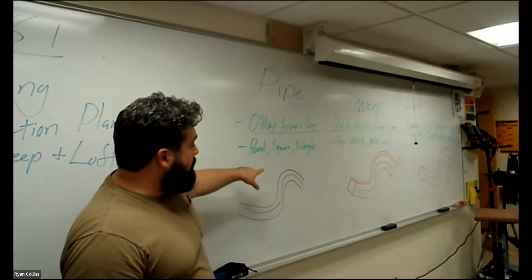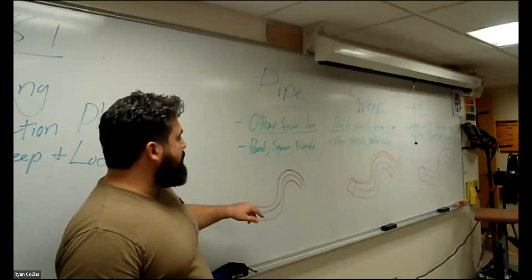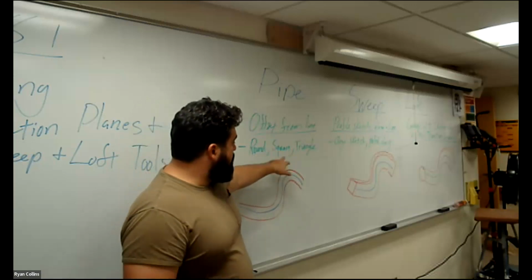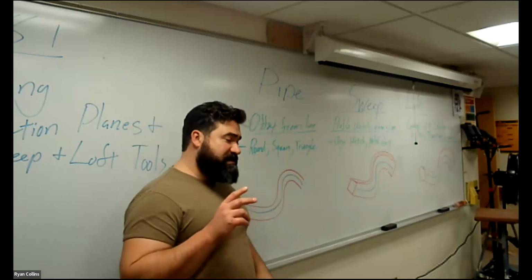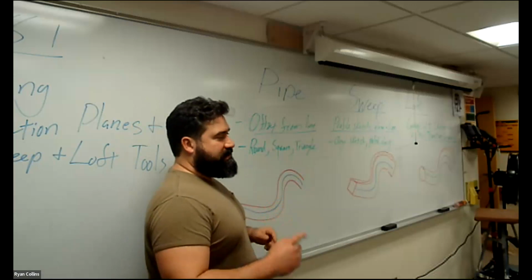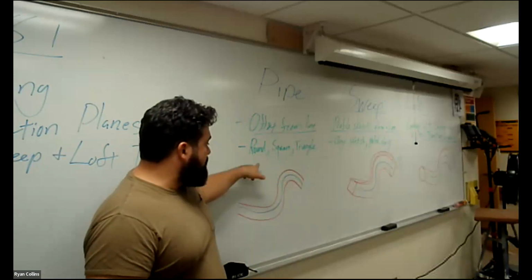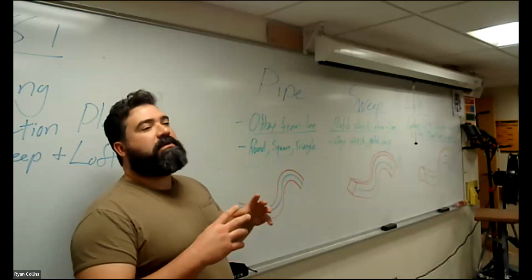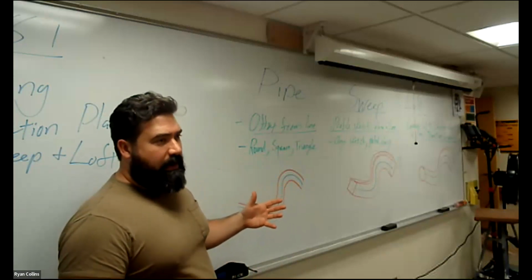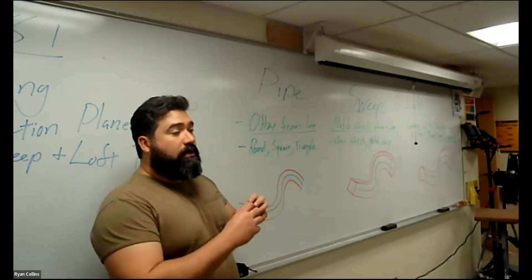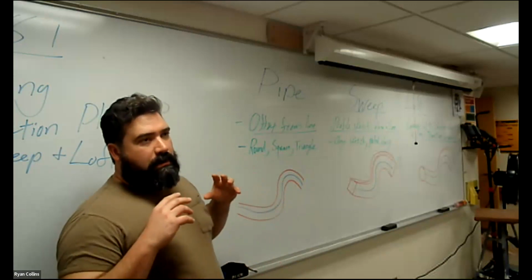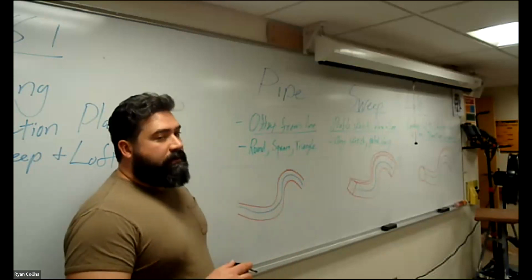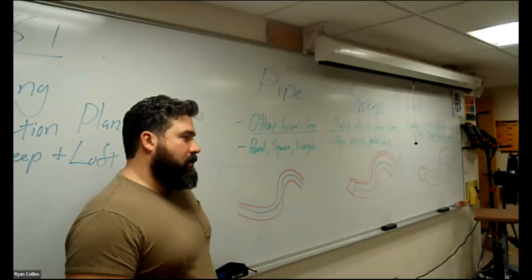Now you have three options. You can make it round, and then you can set the diameter. You can make it square, and it will be square, not rectangular. So if you make it a 2 millimeter round, it's going to make a 2 millimeter offset around that line. If it's square, it will be a square line through that. They also have a triangle shape. The other option is you could make it hollow.